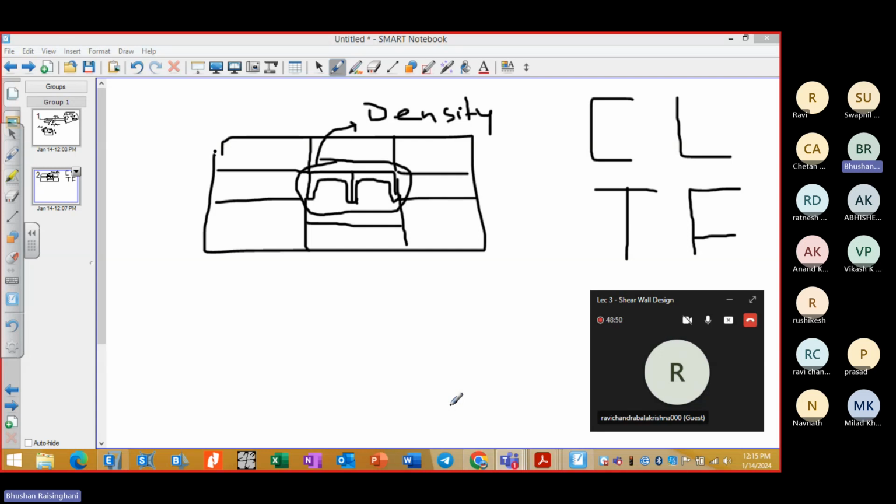So your 100% force, you are assuming that the earthquake force will be taken by the central core wall. But if it is not happening that way and shear force gets transferred to the stairwell, then people who are going to use the stairwell will face severe injuries or fatalities if the stairwell is failing under the earthquake. So it should be protected for the earthquake action. That is one precaution we can take if we have the stairwell separated from the core wall.